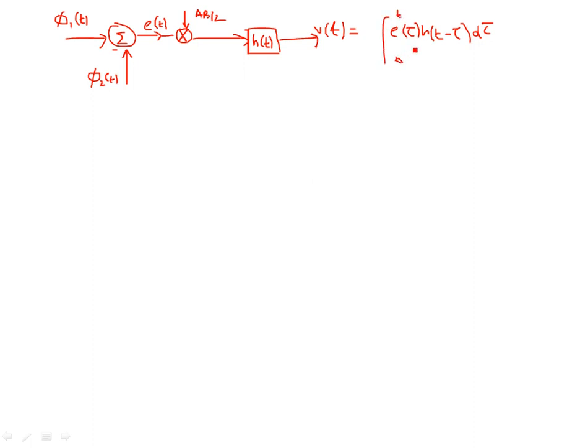Okay, my error signal is the difference of the incoming FM phase and the VCO phase, which is being scaled by the open loop gain AB by 2. Then it is convolved with the impulse response of my filter, and this v of t signal is fed back to an integrator which is modeling my VCO, and this integrator is a scaled integrator, 0 to t dt, and the scaling is with respect to a scalar. If you recall, we have the frequency proportionality 2 pi kV constant. Okay, so that's my scalar. Well, why do we have this? If you recall, what was my phi 2 of t?